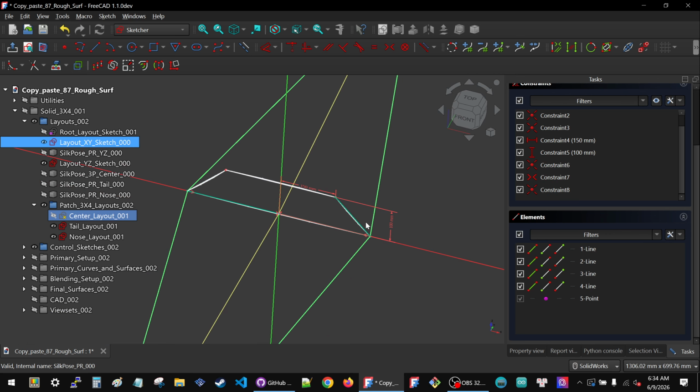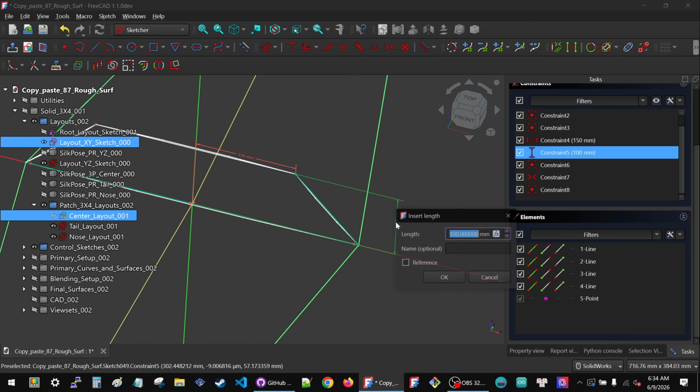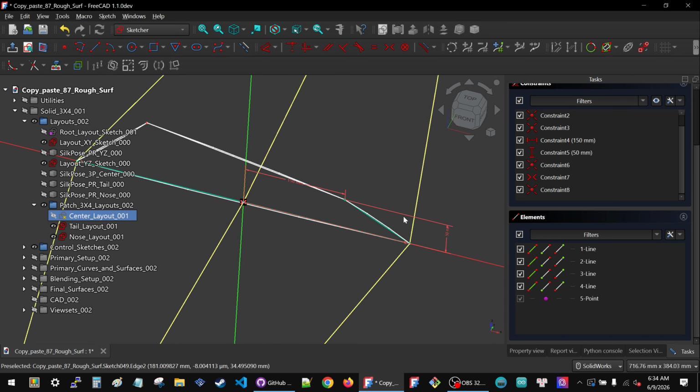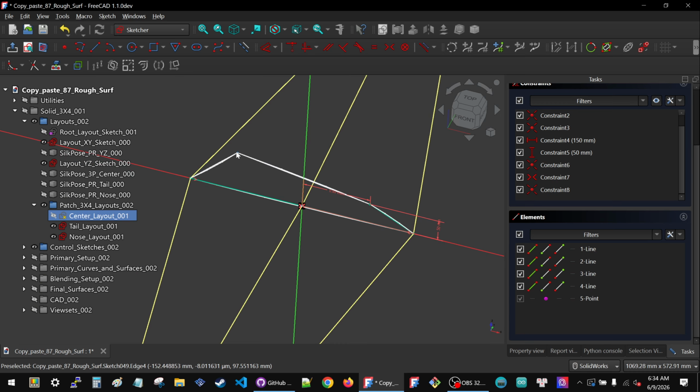Cool. All I need to do is pick dimensions for the height of the rail and the transition from deck to rail. So this is 100 centimeters. This is 10 centimeters. That's way too much. I don't know what a surfboard is supposed to be, but I'm going to say, I don't know, maybe 5 centimeters, so 50 millimeters here for the height. I cut it in half, and the sketches didn't flip out on me. I'm going to drag this one manually close to horizontal,